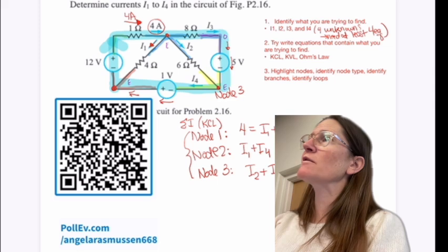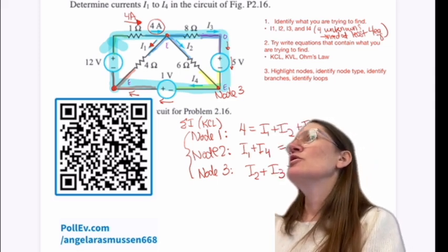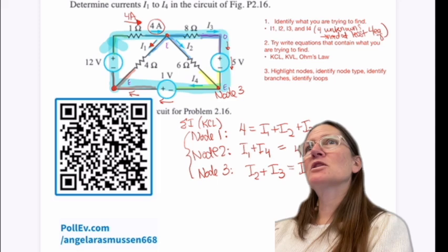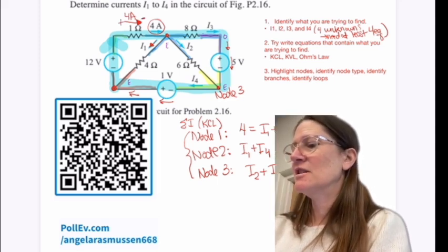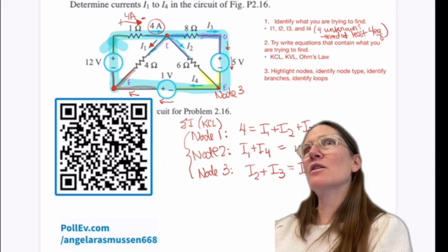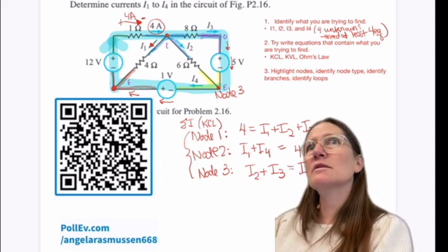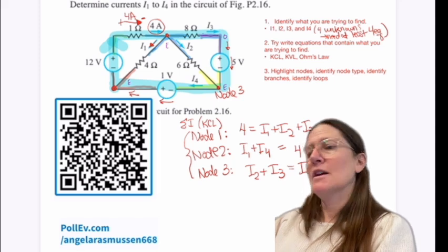So we need to identify the voltage going across each of the resistors. So the polarity for the 4 amp, what's on the left? Correct. And then the right? Negative. So remember, you just have to memorize that the negative means the arrow side. So the negative is always with that arrow side. When you assign the polarity, do you always go with the current? Correct.